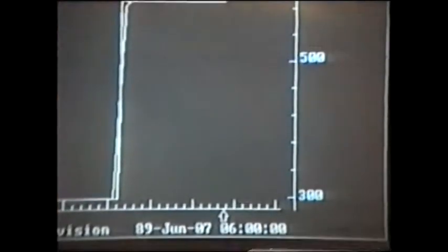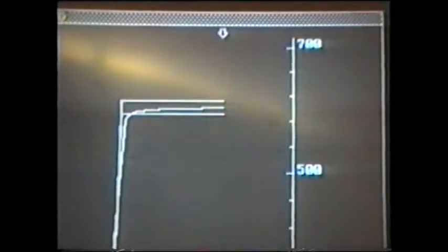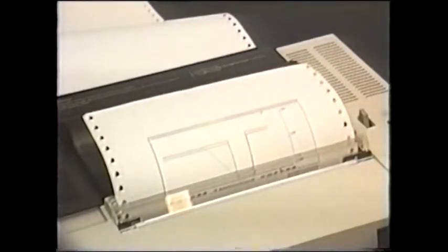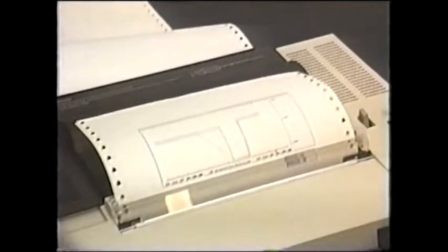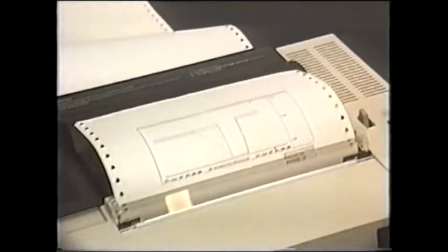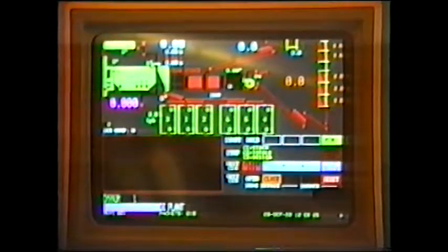On the right side of this graph, the numbers 300 to 700 mean 3 to 7% asphalt content. The graph shown here on the screen can be printed out for a hard copy record of this performance. Imagination is the only limiting factor in creating data logger reports. All the variables are recorded so that a graph can be made based on any desired data for any time period. Other production reports can be produced on demand or at selected time intervals.